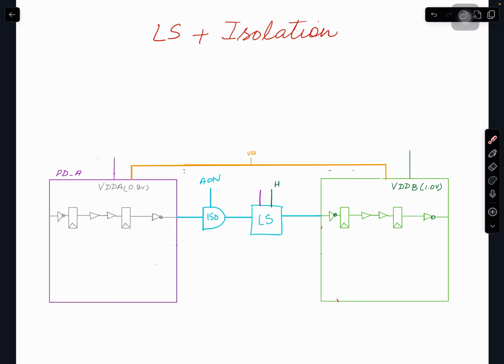You also need to look into the floor plan, but again, we are on the timing side. If you're a designer, you need to ensure this. But in the timing netlist, you will have these things correct. Somebody has already run formal equivalence on the netlist, and somebody has run UPF testing.